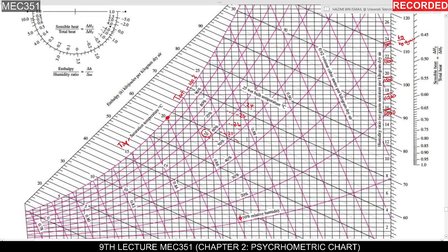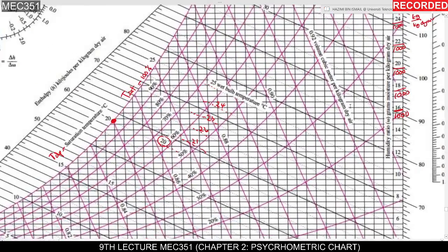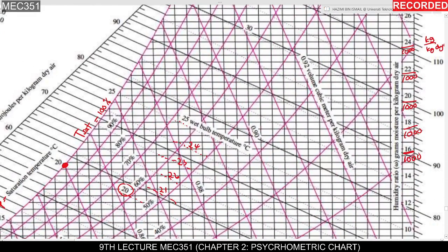Okay. So the other thing is the volume, cubic meter per kilogram dry air here, right? Okay, ni saya tak explain lagi kan. Okay, volume cubic. Apa maksud unit volume cubic? Okay, meter cube lah kan. Volume cubic meter per kilogram dry air. So per kilogram dry air, when the volume is over the mass, this is what we call the specific volume.